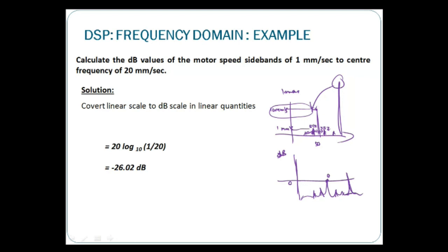So using 20 log 10 V over V reference, you know what its amplitude is in dB. So that is another representation of the spectrum. Conventionally, it can be easily represented in linear, but sometimes you will see this in dBs, especially when you want to compare it with a certain amplitude reference.